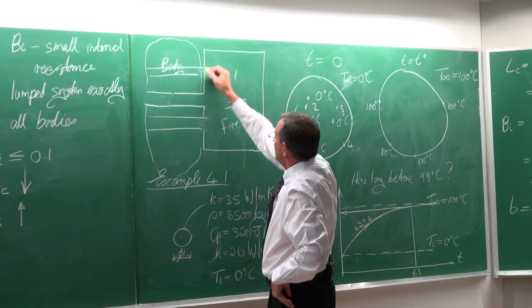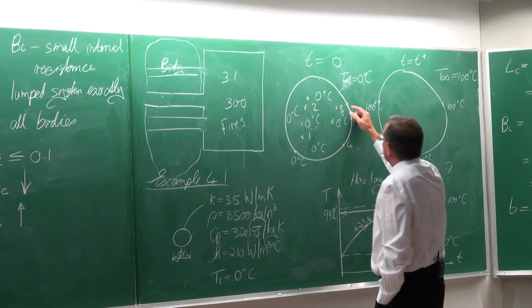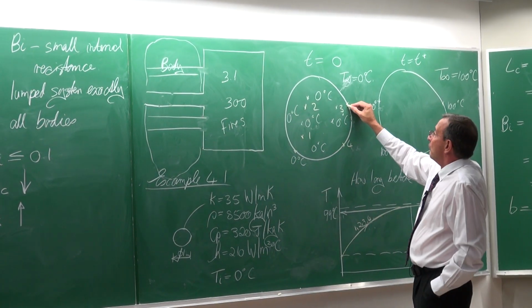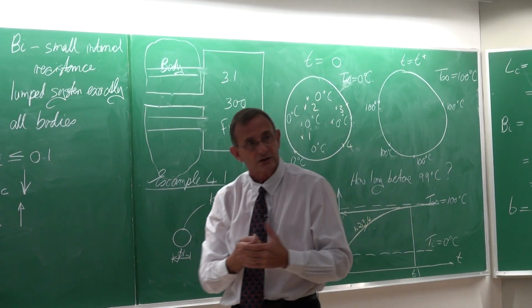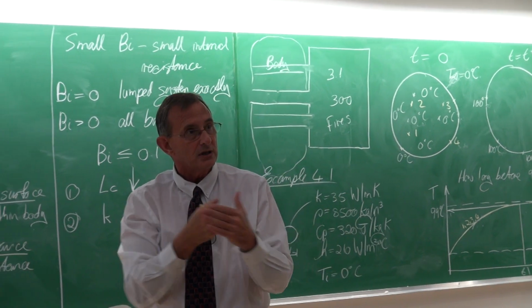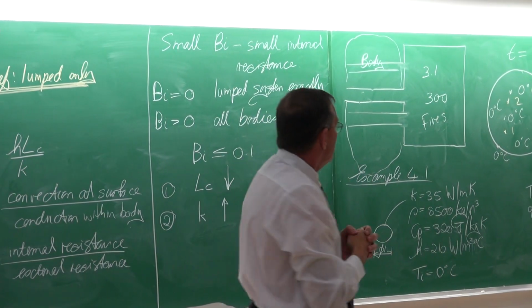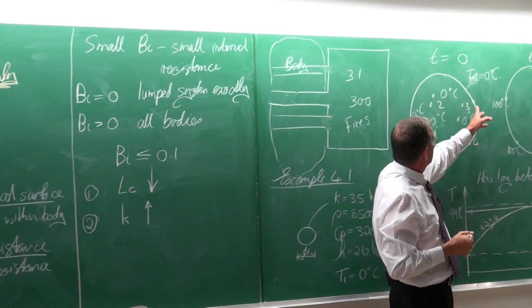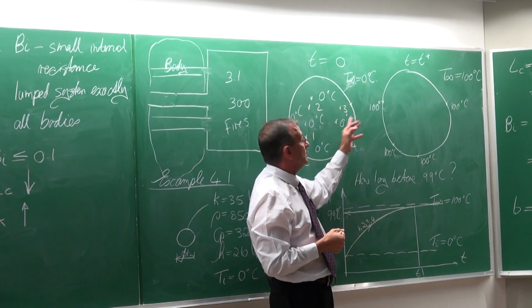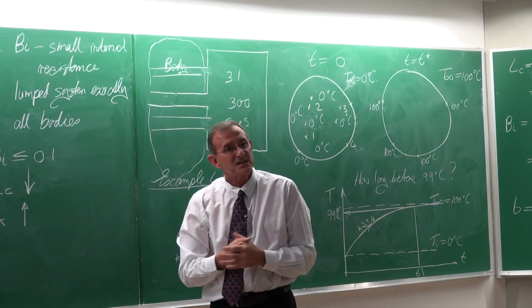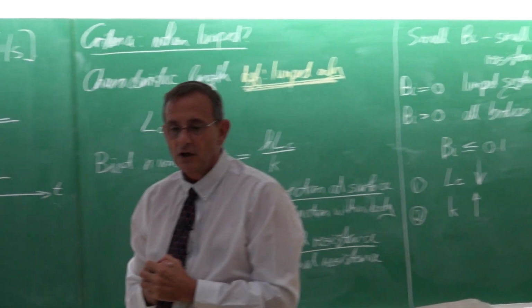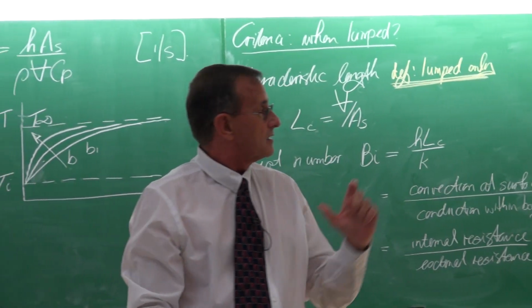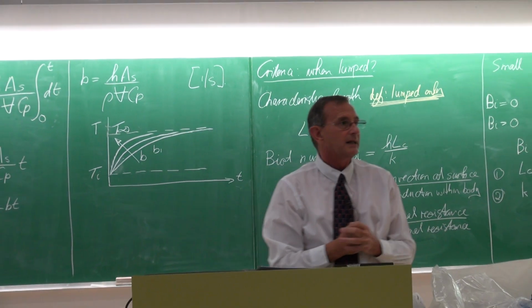Remember, here on the outside, with conduction, we have molecules that vibrate, and that is how the heat is being transferred. They're at a higher temperature and they want to go to a lower temperature. It's the same with flow. If it's at a high pressure to a low pressure, always the same. It is the resistance that determines the flow rate, the mass flow rate, or the resistance for heat transfer that determines the heat transfer rate.